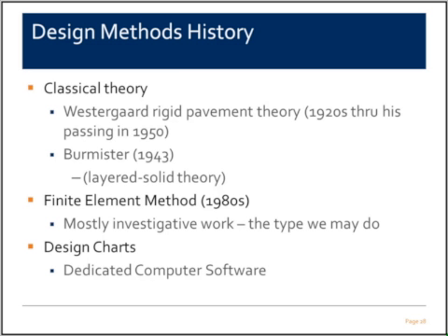And he assumed elastically supported rigid pavement and real loads on that pavement to come up and solve a bunch of differential equations to come up with his equations for slab design, which has stood through the test of time, but it assumes full contact between the slab and the soil, and it has been found that if you lost contact due to, for example, curling, then it might be not as good a method.